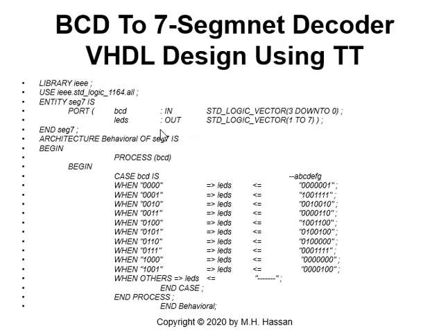And the output, which we call LEDs, will be out, also a standard logic vector 1 to 7, because we have 7 outputs. The segments A, B, C, D, E, F, G, what we call here LEDs for simplicity, and it is standard logic vector 1 to 7. Then I will end my entity named SEG7. Architecture behavioral of SEG7 is, as we begin.